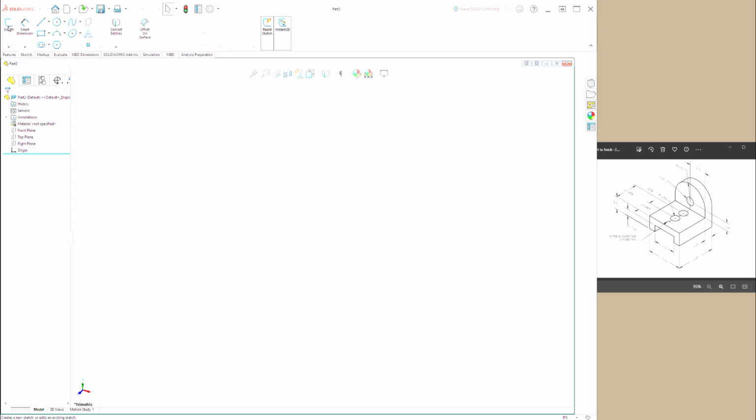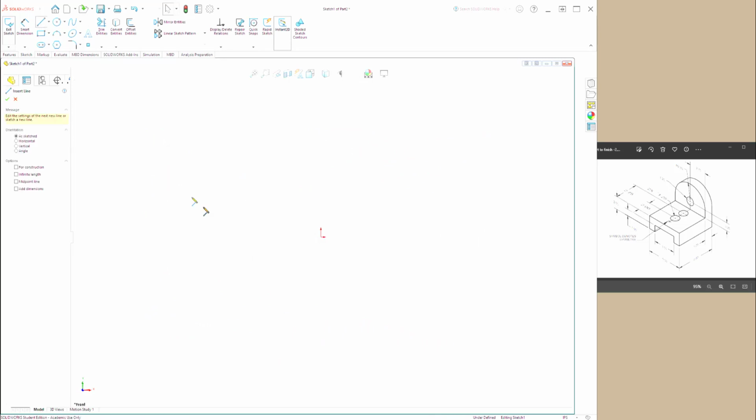We'll pick the sketch button, and we're going to work from the front plane on this particular drawing. And on the front plane, we'll start at the 0, 0 point, and we'll sketch out the L shape. So we'll start at the anchor point, bring it out. I'm not worried about what sizes the dimensions are. We'll deal with that in just a minute. But the whole idea is that we need to sketch out the L shape.